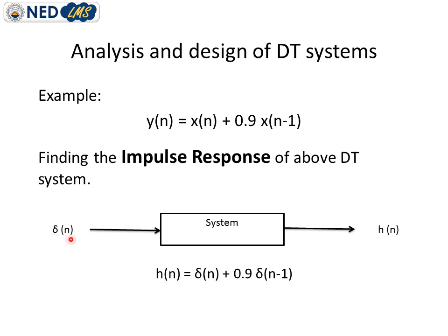So with the help of this information, we are going to find the impulse response of this system using the given difference equation. What we need to do? We just replace the input by delta of n, and we replace the output, which is y of n, by h of n. As we already concluded, whenever an impulse is applied to the system, it will yield the impulse response.